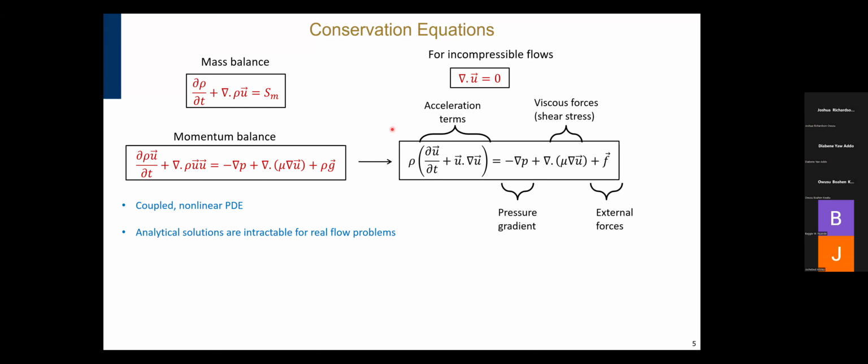You would most likely get a solution valid for a lab scale crystallizer. But once you begin to scale up, that is where all of those mixing challenges pop up. That's when people turn to people who do CFD to help them come up with a mixing strategy. So those are some of the things you have to consider.